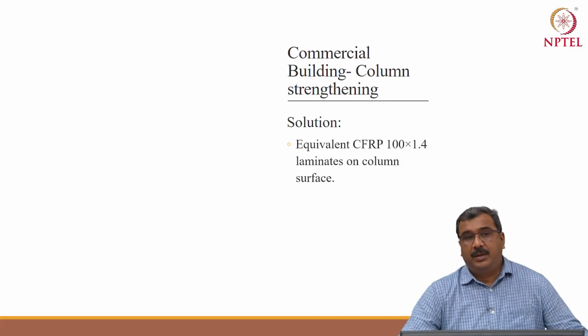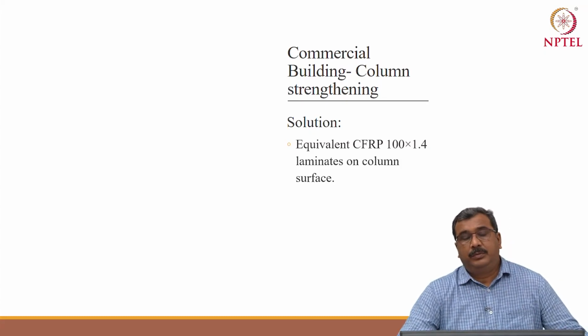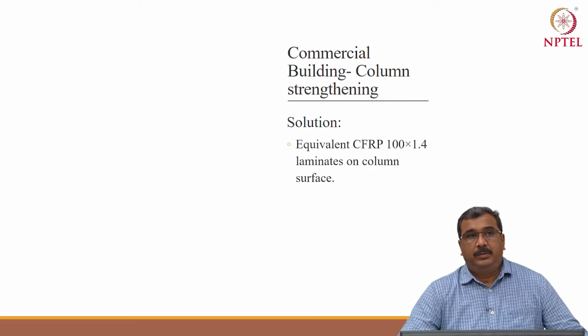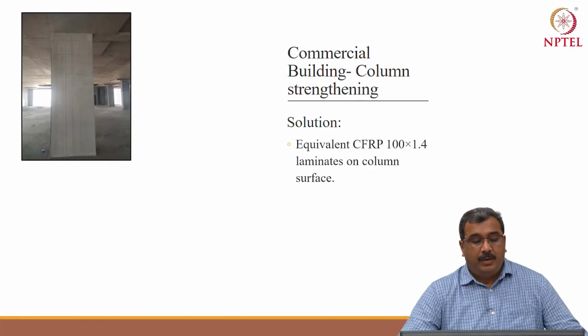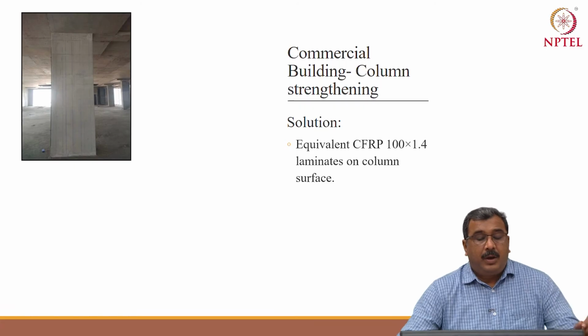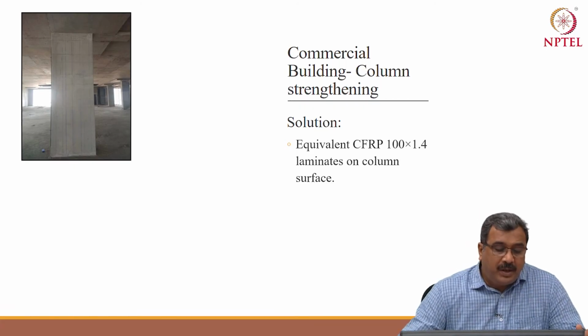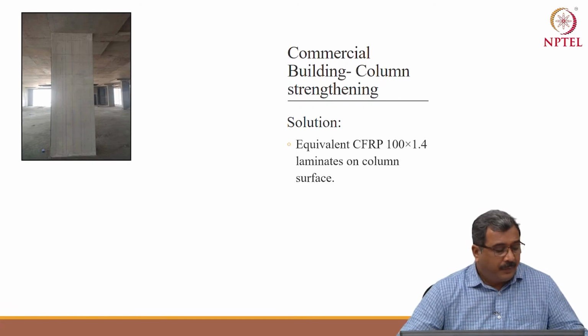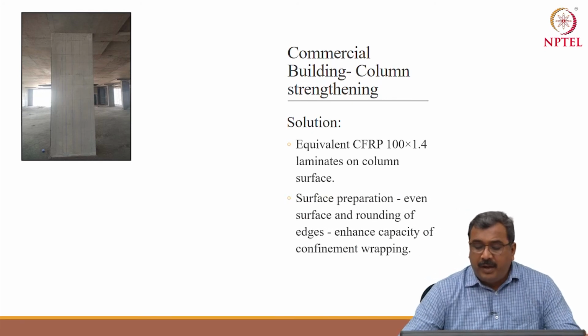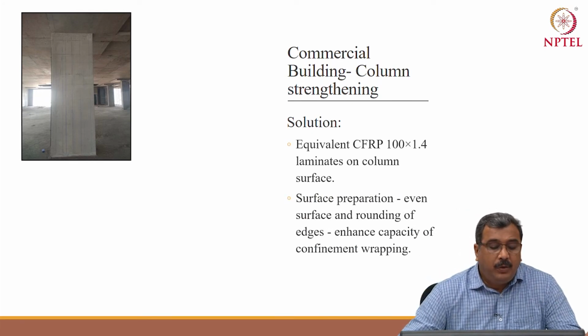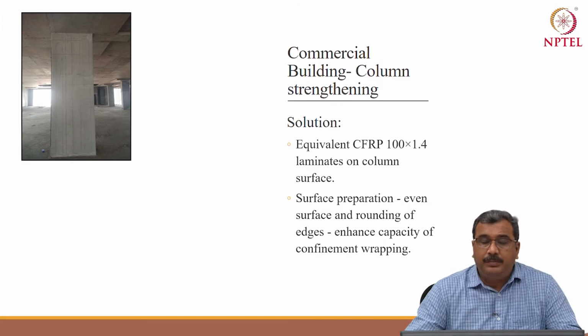Once the numbers have been derived, proper care has been taken for junction development, that is, to transfer the load from the column capital to the column. For the column which was to be strengthened, proper surface preparation has been done to even out the face of the column.